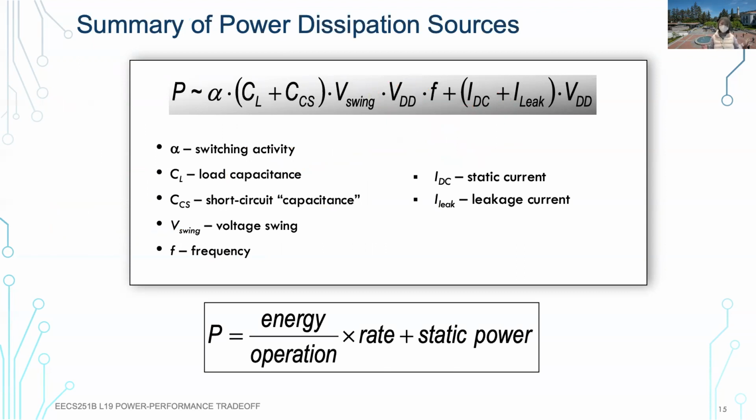power, again, power is really a rate of energy consumption. It has both a dynamic component, CV²F, which is very related to the switching activity. We'll see more how we modulate based on the switching activity. But the static power is also getting a lot more important these days. This has become a very significant part of the power optimization. So that's the basics of the different power metrics that we're using, different trade-offs in this space, and different components and sources of power being evaluated.